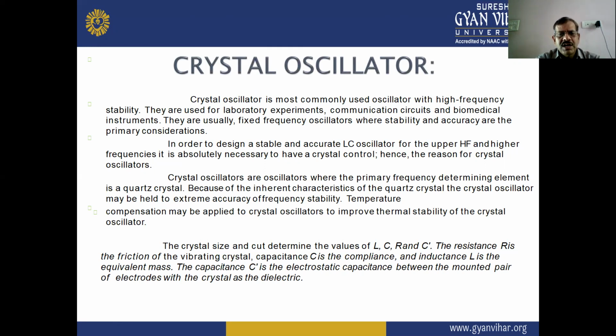In order to design a stable and accurate LC oscillator for the upper high frequency and higher frequencies, it is absolutely necessary to have crystal control, hence the reason for crystal oscillators. Crystal oscillators are oscillators where the primary frequency determining element is a quartz crystal.